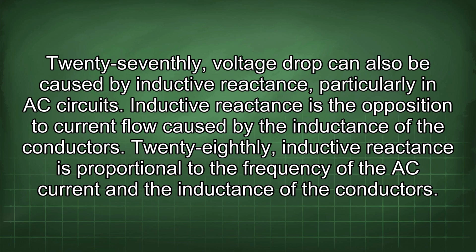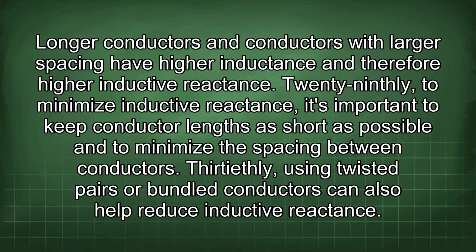27thly, voltage drop can also be caused by inductive reactance, particularly in AC circuits. Inductive reactance is the opposition to current flow caused by the inductance of the conductors. 28thly, inductive reactance is proportional to the frequency of the AC current and the inductance of the conductors. Longer conductors and conductors with larger spacing have higher inductance and therefore higher inductive reactance.